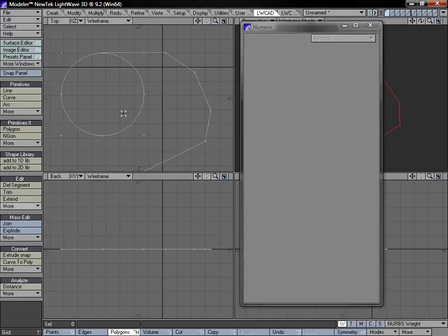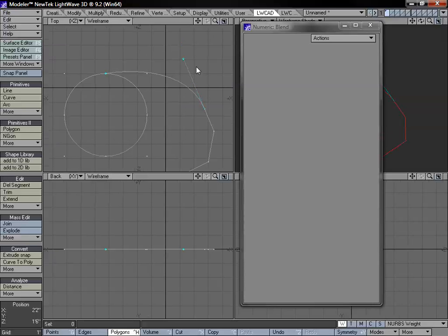The next thing we're going to take a look at is the blend. So I'm going to undo this, and let's go to our blend mode. Now you can see I clicked on our top and this line over here. It's the top of our circle and this line, and now we have the ability to draw a curve out and blend these objects together a little more manually. And keep in mind these lines that we have are going to be projecting directly off of our specified line, and they will stay in that angle. So depending on what it is you're working on, you might need to select different points to achieve the kind of effect that you want, or even just use a variety of different points.